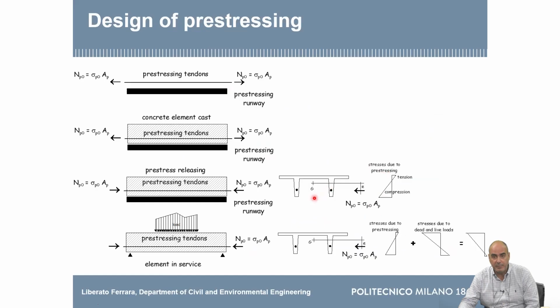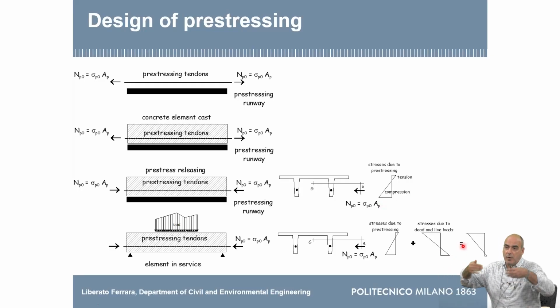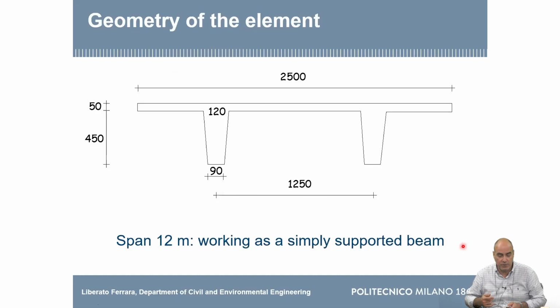When you release the pre-stressing, you expect stresses like this. So the compressive stresses are in the bottom. Whereas in the other design stages, because you apply the load, the compressive stresses will go on the top. So at 16 hours, 20 hours, or whatever, you accept the higher stress, but in a region where that stress will progressively be relieved by other load situations. So that is the reason for which we do this.